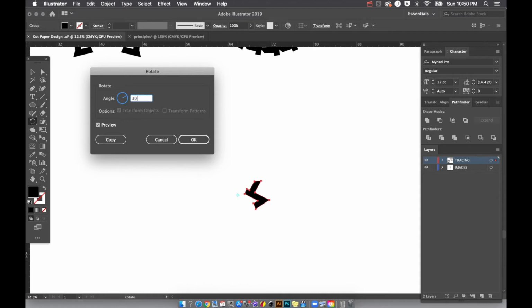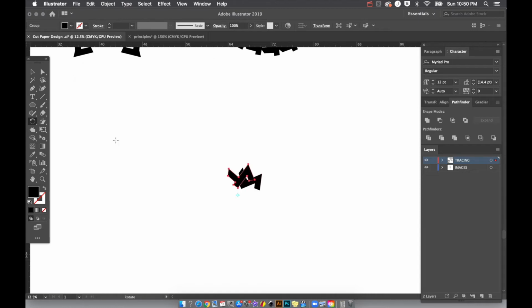I'm going to use an angle here that goes into 180 degrees perfectly, and make sure that I do that rotate by copy. Command D is the keyboard shortcut for repeat, and this allows me to repeat that design all the way around. And as I do that, it gives me a lot more control over what that design may look like. I'll come out here and do that one more time.